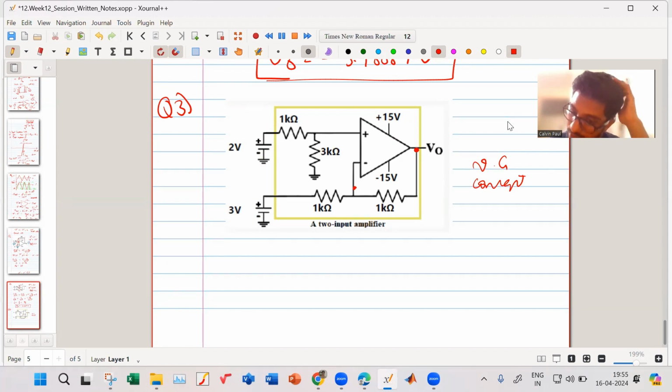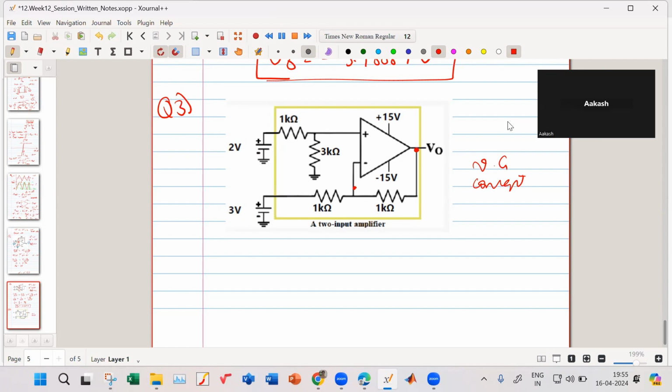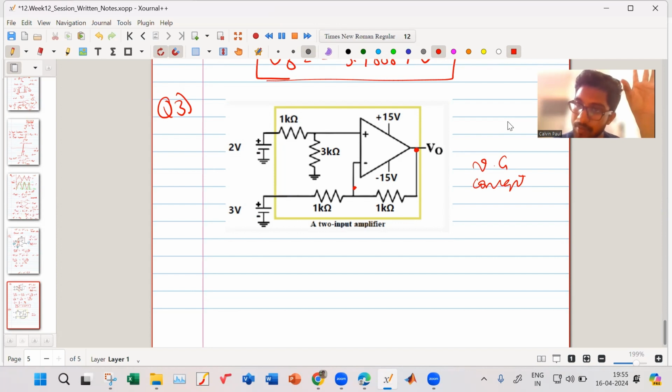And negative feedback is very useful. It's a concept you will find almost everywhere in your electrical networks, as a system level concept, because it improves stability. It's not always true that it will improve the stability, but it is a way in which you can regulate and control your output. So open loop is not always good. You need to have closed loop in many applications. Okay. So now in this case, we will apply the virtual ground concept because the output voltage signal is being fed to your negative terminal.